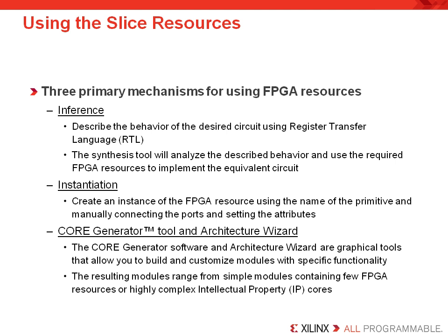A primitive is a resource that is written to the netlist that represents a particular FPGA resource, such as a LUT, shift register LUT, distributed RAM, etc.